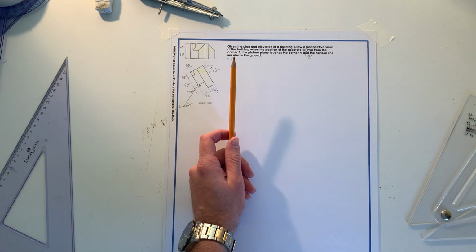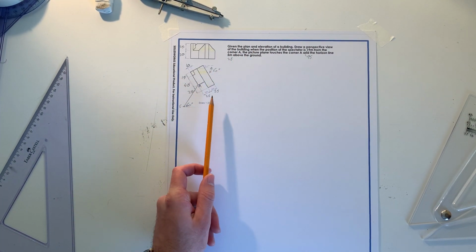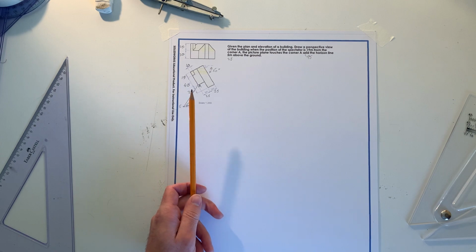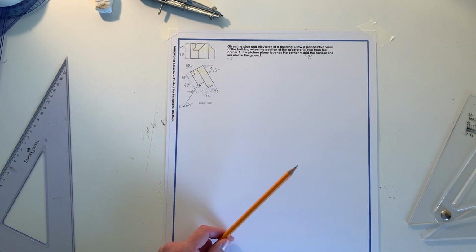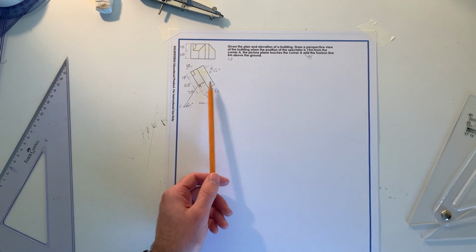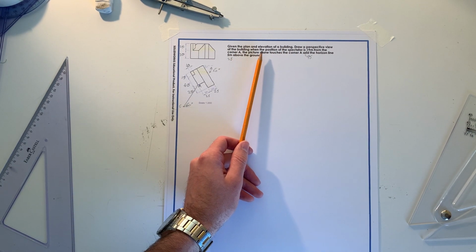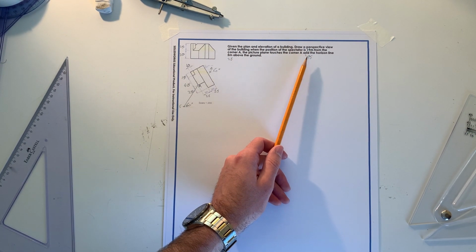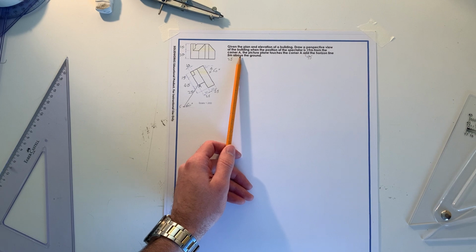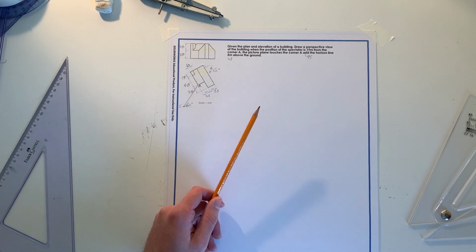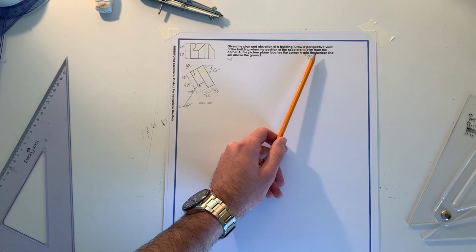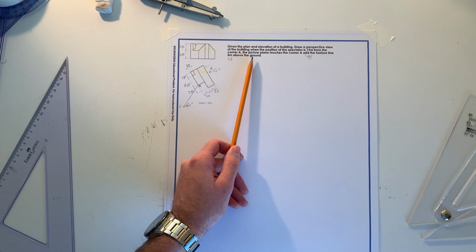Now if we have a look at what we're given, first of all I just want to identify here the reason that I've changed all the numbers around the side is because it's a scale of 1 is to 200, so I divide all the measurements by 200 to get the measurements we need in millimeters. So given the plan and elevation of a building here and here, draw a perspective view of the building with the position of the spectator at 19 meters, which in the change from scale is 95 millimeters from the corner A. From this corner A below here in plan, the picture plane touches the corner A and the horizon line is 5 meters above the ground line, which is 25.